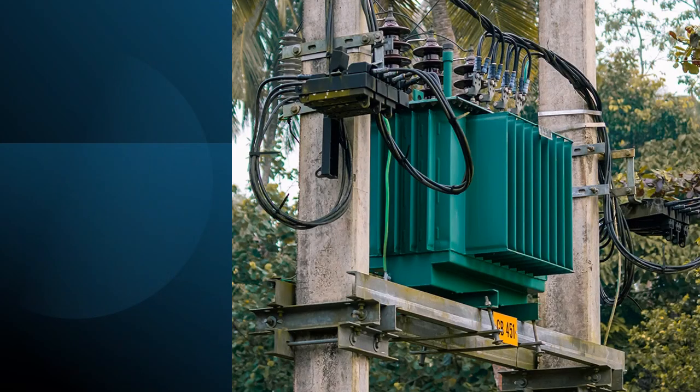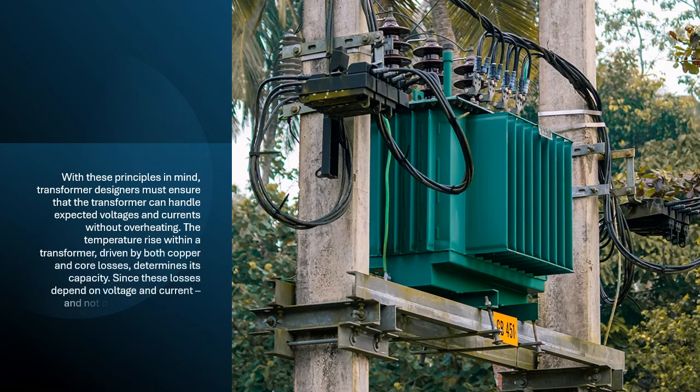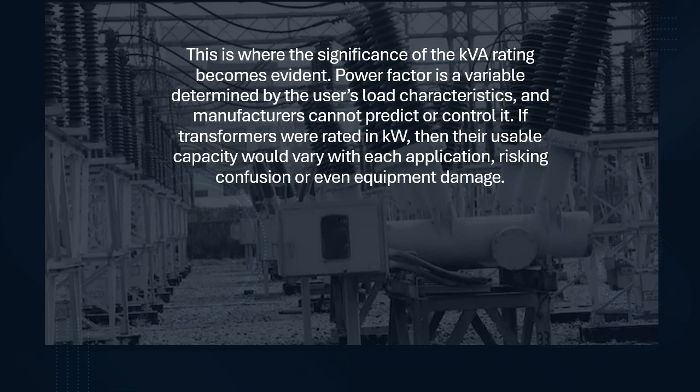With these principles in mind, transformer designers must ensure that the transformer can handle expected voltages and currents without overheating. The temperature rise within a transformer, driven by both copper and core losses, determines its capacity. Since these losses depend on voltage and current and not on the power factor, transformer ratings need to reflect this directly. This is where the significance of the kVA rating becomes evident.